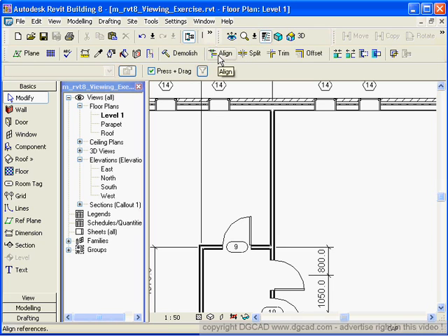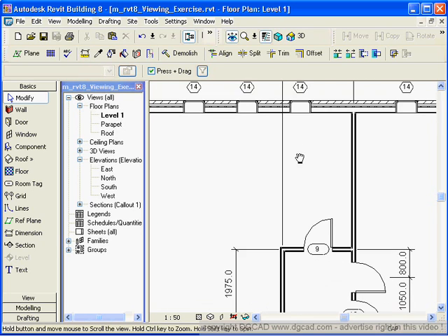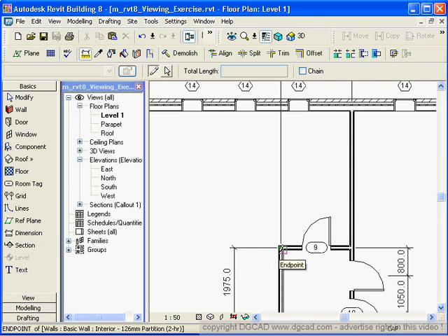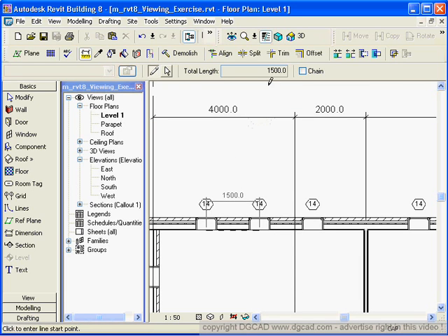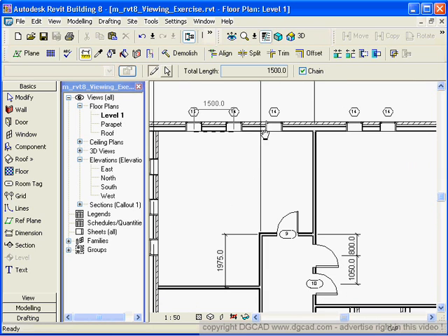And last, a couple of closing commands here. We've talked a fair bit about the align command. If we want to do temporary, if we want to measure something while we're drawing, and we want to know what the distance is, we can also go inside of here and pick on here and then pick over to there. It'll tell us the dimension inside of here, sometimes you can't read that. And it's one of those looping commands where you can go in and do a bunch of them. What I call persistent commands, so we can go from here to there, and then it'll show us these temporary dimensions, and it'll also reflect that dimension up in there, which isn't going to change, purely for information.